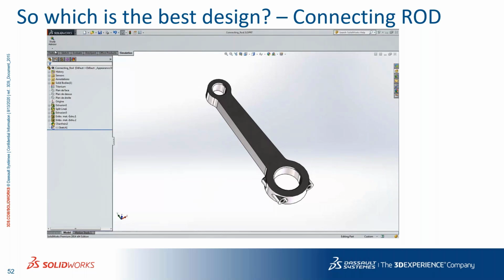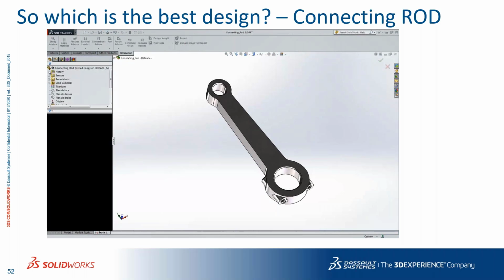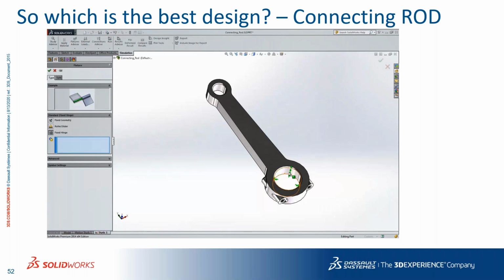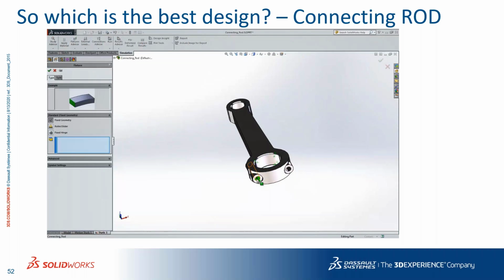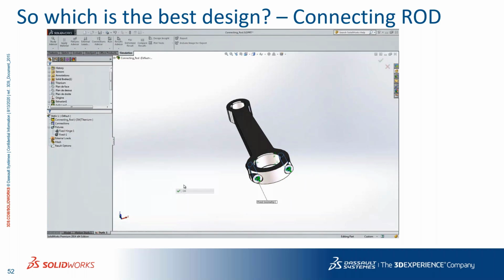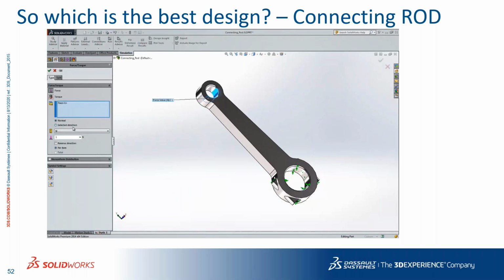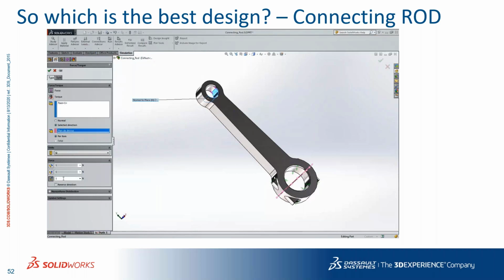When you go to the SOLIDWORKS environment, I will just go for a new study. I'll tell you the procedure I'm going to perform here. I'm going to apply the fixtures I defined, the hinge connections at this location. Then I'm going to add the fixtures, which fix it with the help of bolts or connections here. I've added a fixture in this portion, and here I'm going to apply the bearing load, the forces, and I can take help of different planes to define the direction in which I want to apply it.